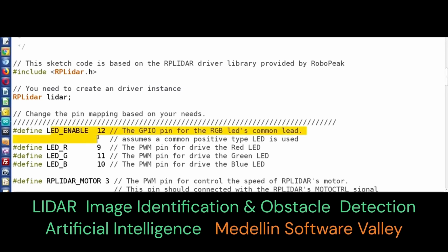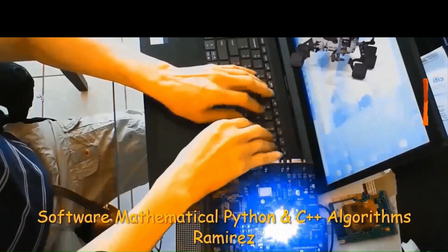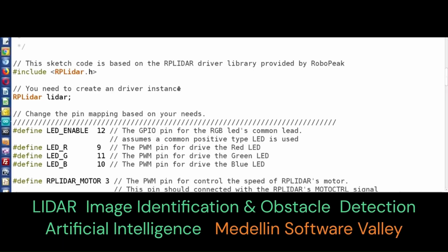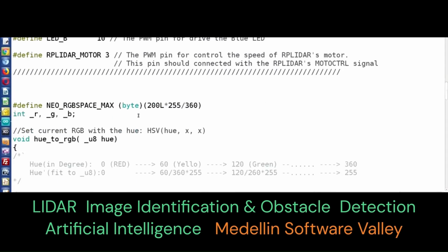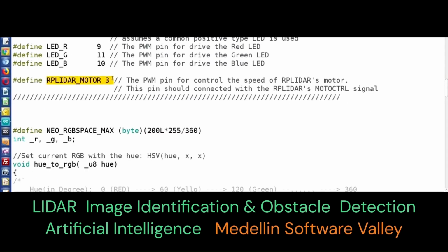The mode pin is inserted which places the sensor in analog input or analog output mode, and as a result, each distance corresponds to an analog output value that must be sampled by the analog to digital converter, which is the ADC, at the host side, at the CPU side. And then it will take the data using the I2C protocol.